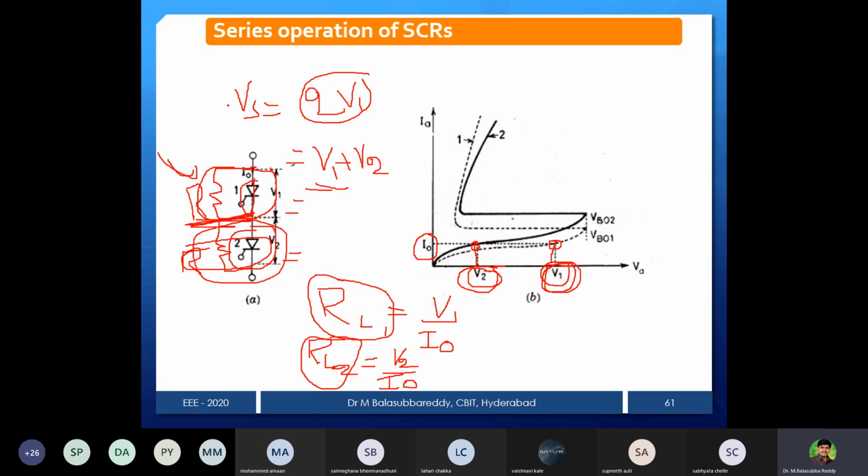You derive one resistor value by considering the leakages, blocking voltages and drops, the total string voltage, and the number of SCRs in series. Taking all these parameters as inputs, derive one expression such that the value is the same for all the SCRs in series.